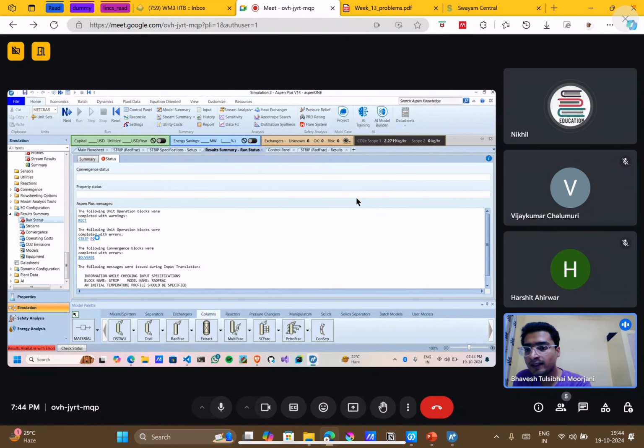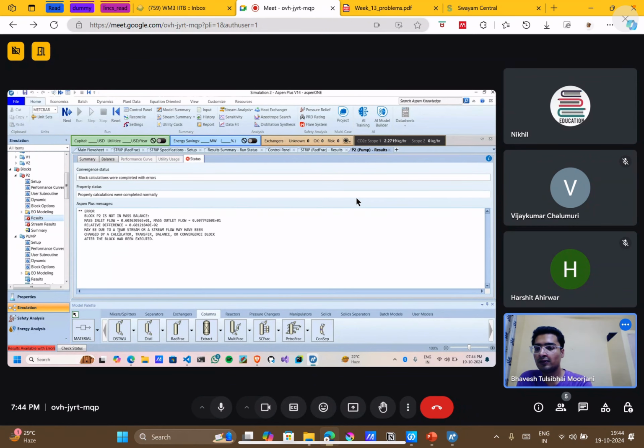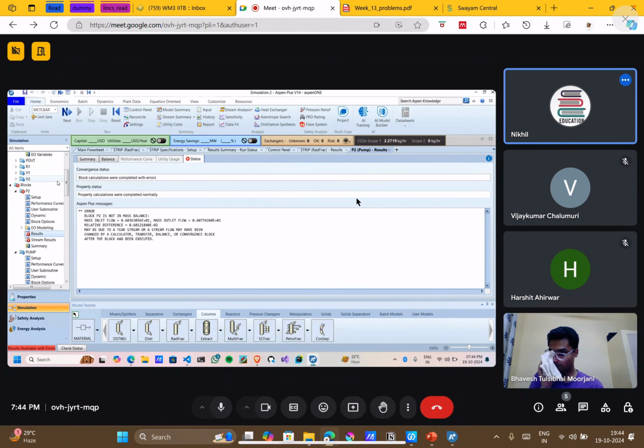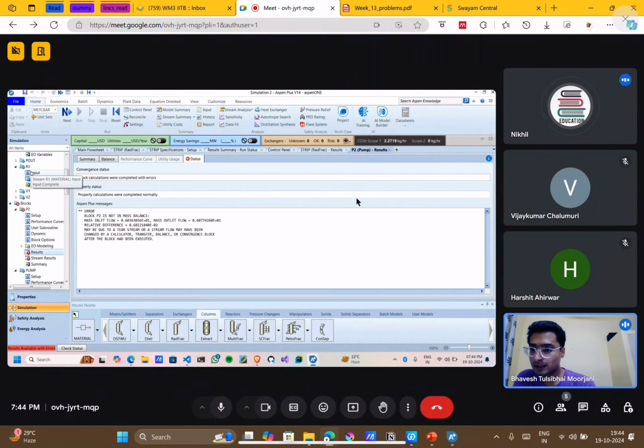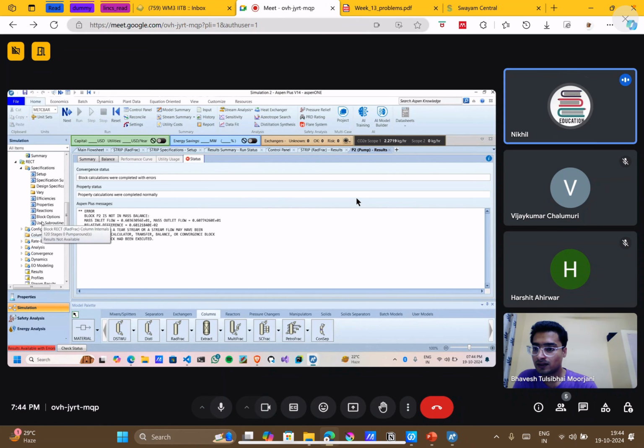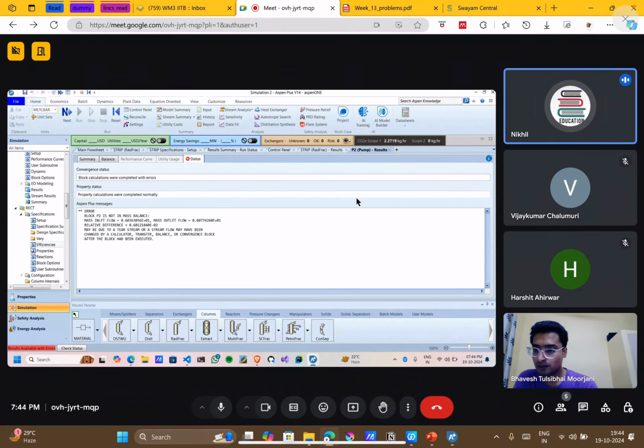Click on the RECT, go to the stream summary of the rectification column. No, not this one. Go down. Rectification, RECT, that we have given. Here. Yes. Go to the stream summary of this block. Go down.